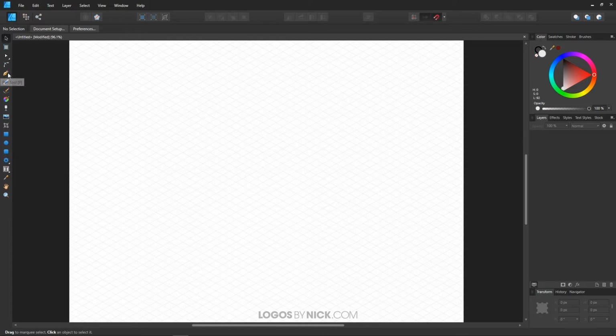I'm going to grab the pen tool, which is over here, or you can just press P on the keyboard. And I'm going to start over here to the left side. I'm going to snap to an intersection right there, two intersecting grid lines. Click, and then hold Shift and bring this line straight through. Now I'm going to bring this a number of segments away. 1, 2, 3, 4, 5, 6, 7, 8, 9, 10, 11, 12. So 12 segments away. If you notice in the guideline there, there's the number 300 populating between that. That's just a measurement to tell you how many pixels away the lines are. So I'm going to use 300 for this side.